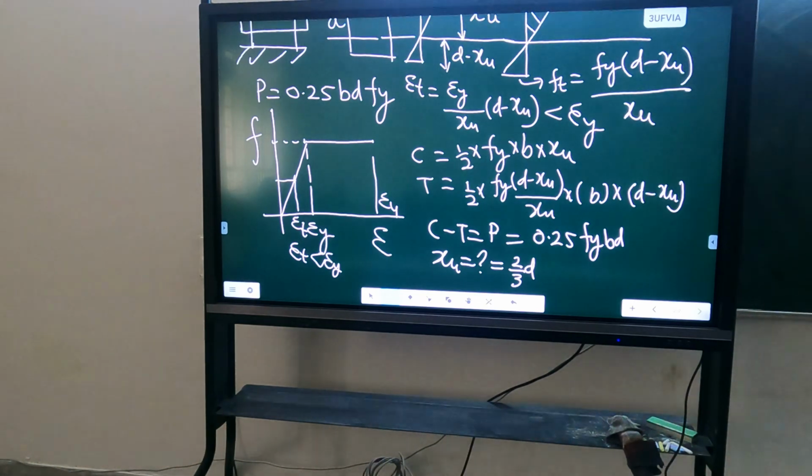So all the analysis is done about the centered axis. When you do matrix analysis and make a computer model, you represent a column by a line. Where is that line? At the center. So all the analysis is done considering the centered axis, and that's why in the design, we are calculating the capacity about the same axis.